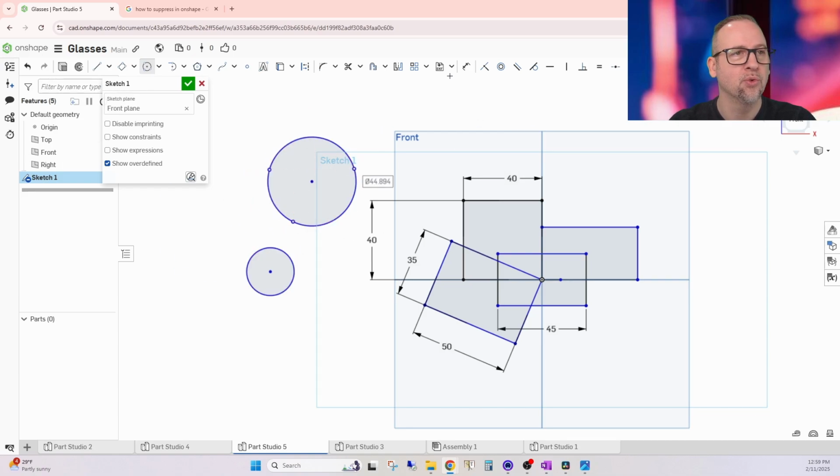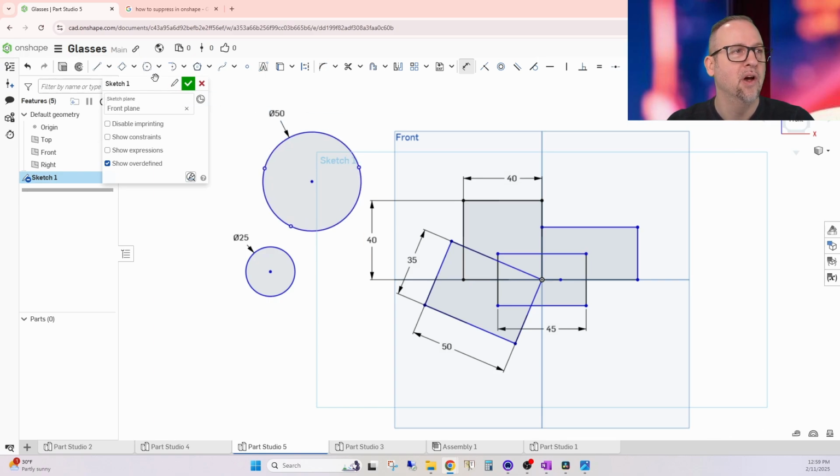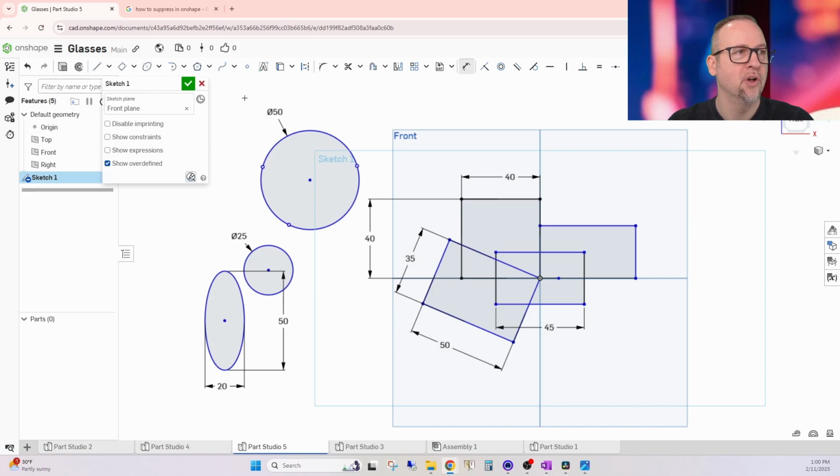And one thing with circle is you can always go to your dimension and you can say this circle is 25 millimeters around. Okay. And then the same thing here. We can put a dimension and say it's 50 or so. Okay. And then the last one was the ellipse. The ellipse will give you your height and then your width, so you can change that, and that's modifiable too with your dimension here. Let's see. Okay, so it did the width to say this is 20, and the height of it should give me a height here. There, no, okay. Go again. How about just pull it off the side and get you that? So you get your height there. Okay. So there's your ellipse.